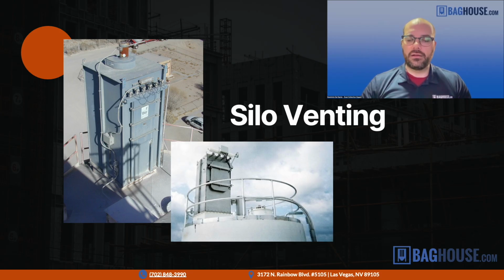Where they are used differently many times, though, is whereas a baghouse usually is pulling air from something with its own fan, bin vents are usually placed on top of something where you're pushing air or pushing material into. So the most common place is on top of a silo, or sometimes weigh bins or very large day bins.